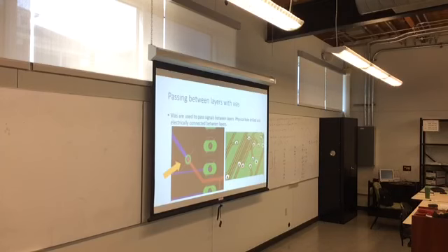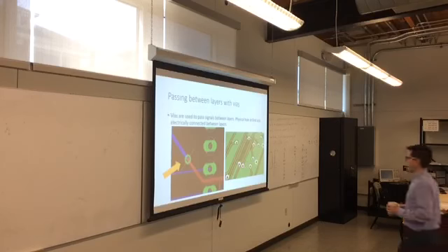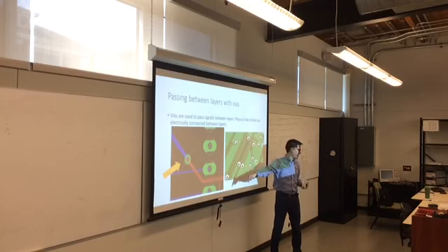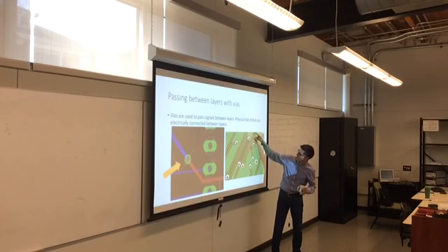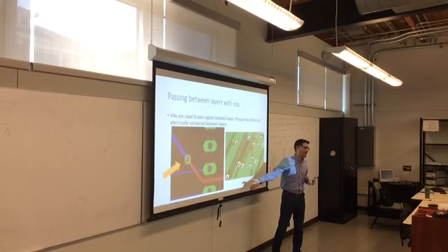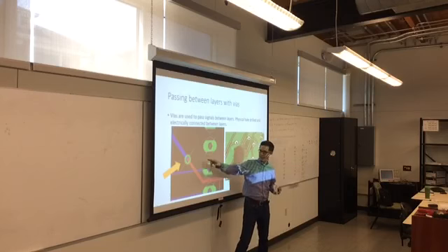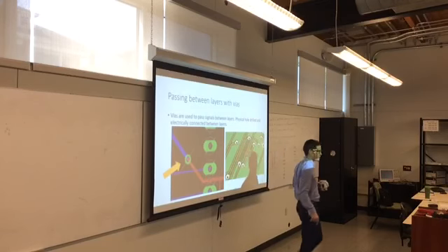So if it's a through-hole component, it is drilled all the way through the board so you can solder it on the other side. If it's just dropping a signal from one layer to the next, it's a via, such that here is a signal that is coming up from another layer and then ending up on this layer. This signal is already on this layer and is using the via to go down to another layer. It's like an elevator for signals. But it does cause a hole. It is a smaller hole than a through-hole component, but it is sort of an electrical hole.